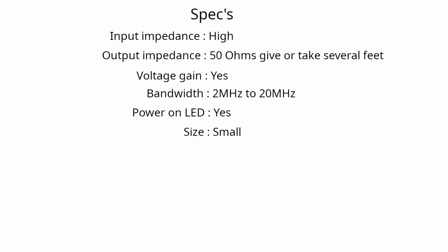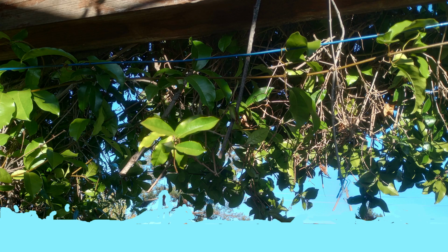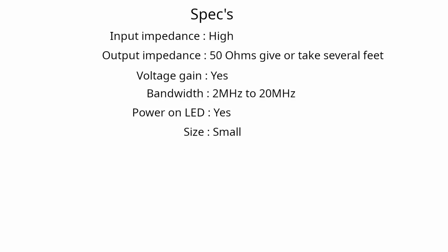Before we start designing an amplifier, it is good to set down some specifications for it. I carefully measured the impedance of a piece of wire stapled to the vines, and found that it was about 300 ohms, and this is the impedance that we need to match to. The specifications for the SDR say that its input impedance is about 50 ohms, and matching this low impedance to the much higher impedance of the antenna is the main purpose for this amplifier.